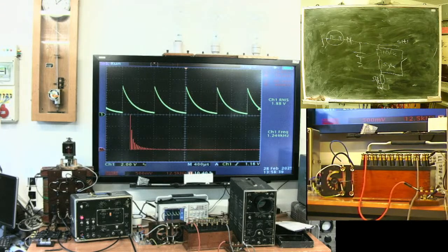The fast rate of change means more high frequency components. More high frequency components, shorter life of semiconductors. It's reality. That's why sometimes snubber networks are introduced: RC networks connected in parallel to suppress high frequency components.